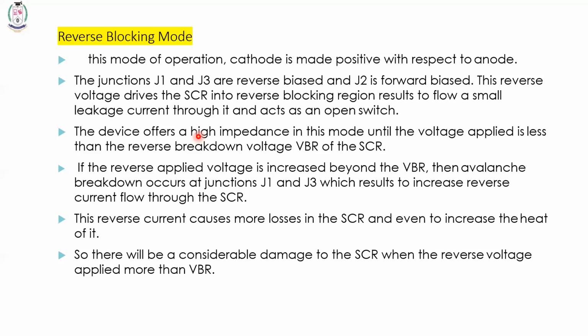If we keep on applying the reverse voltage, then obviously avalanche breakdown will occur at J1 and J3, and then reverse current will flow in the SCR. If we apply even more reverse voltage, that will cause considerable damage to the SCR.